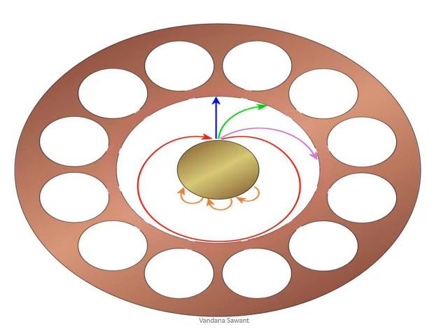Then, if we increase the magnetic field above the critical field, the red color path is taken by the electron, and the electron will move for a larger distance, and that is not advisable. It will come back to the cathode and heat the cathode. Similarly, if we go on increasing further, many hops of electrons take place. Electrons will come out of the cathode and go back to the cathode immediately, and that will heat the cathode and the device. That is also not advisable.